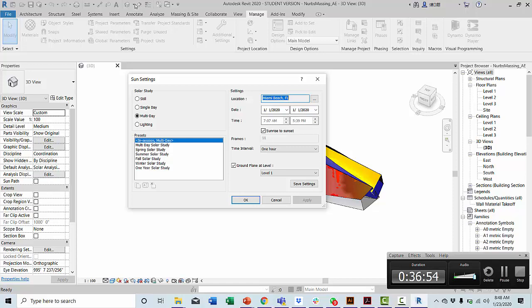Same thing for winter. You do the same thing. You go in the middle of winter and pick the coldest day of the year, and then run the analysis and see how maybe you could then optimize for direct solar gain by adding a window on that south facade in the northern hemisphere, right? So that way you can use the sun for heating as a passive strategy. So you have different, as you can see, you have different ways of approaching this issue.